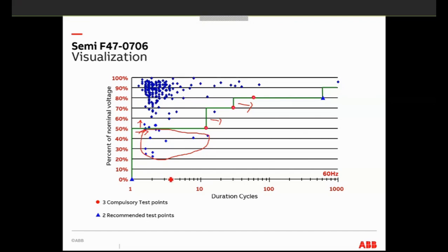All right. Okay, so what you see here is in cycles, not in milliseconds. If you have 10 cycles here, it means 200 milliseconds. So this is very fast. We are actually seeing this graph here because we were able to zoom in on the voltage sag event.